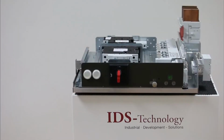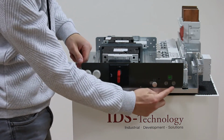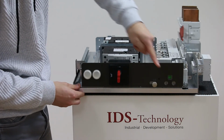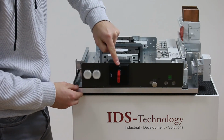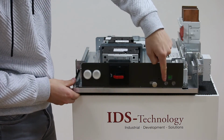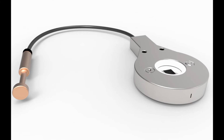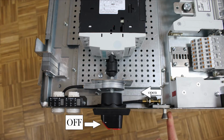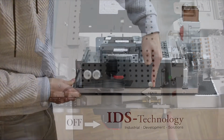To repeat these steps again with the completed drawer, we'll explain the mechanical interlocks. The operating holes are normally closed by a movable latch. The operating holes can be opened by pulling the operating latch to the left. The operating latch is interconnected with the high flexible ELD, easy locking device, which is blocking the operating latch when the MCCB is switched on, because it's only allowed to operate the contacting module when the MCCB is switched off or the drawer is de-energized.